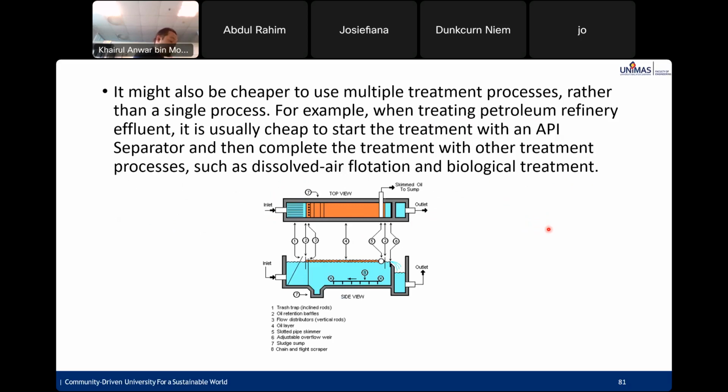So meaning for the removal of the contaminant, the wastewater treatment is normally not a single process. So, for example, if the system requires filtration up to ultrafiltration, before the ultrafiltration they need to have several treatments before the wastewater reaches ultrafiltration.